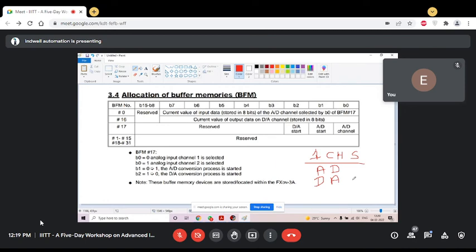As you have connected transmitter to channel terminal, so signal will come to channel, but it will not convert that into digital, or into analog. You need to send command, now start conversion, then it will start converting, and then you can work with this. Nowadays it is by default set, but mostly it is like that. You have to select the channel. Now the rule for channel selection, AD start, DA start is different in different PLC.